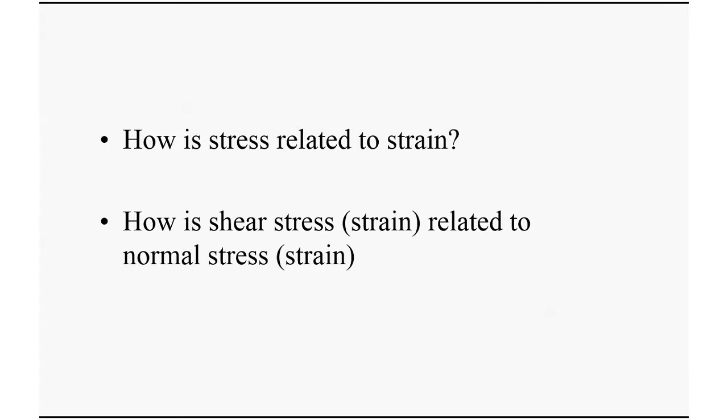Okay, so last time we talked about what the internal force is. Basically, when you look at an object, you want to find out locally, inside, what the force is there. You make a cut, and you find the force there. That's the internal force, right? And then we defined stress and strain. So it's basically the intensity. For stress, you look at an area where you cut, take the total force, and divide by the area. That gives you the stress.